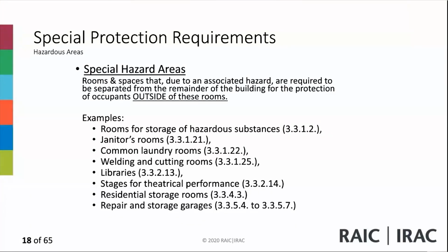So if your building construction allows, as determined in 3.2.2, when we looked at the building construction classification and the type of construction and the floor ratings, if the floor rating is required to be only 1 hour, in this case, when the building is not sprinklered, I can have a janitor's room with a 45 minute rating, right? To be less than 1 hour, but not less than 45 minutes.